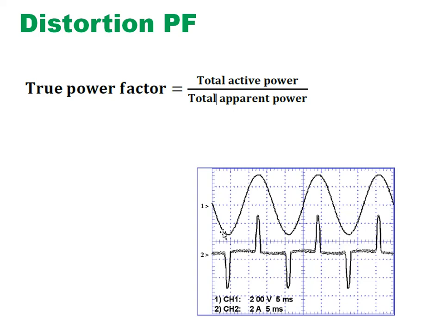In those cases, the supply will be the same amount of supply I am showing here, but the current consumed is in phase with the voltage only in part, not exactly as it is here. This is one cause, called the distortion power factor issue. The waveform is distorting here. And one more factor for distortion power factor is harmonics. Due to harmonics also, distortion power factor will happen. In this case we can't say the power factor is simply the ratio between the voltage and current. Correct?